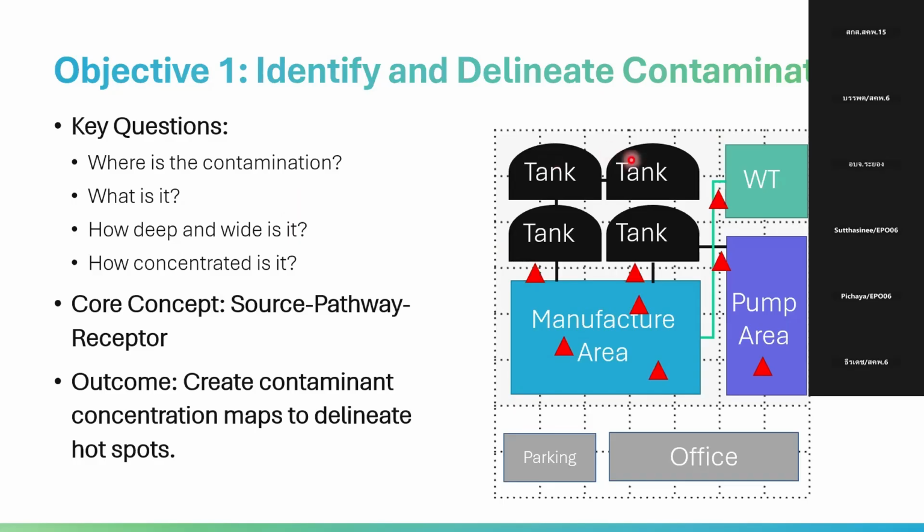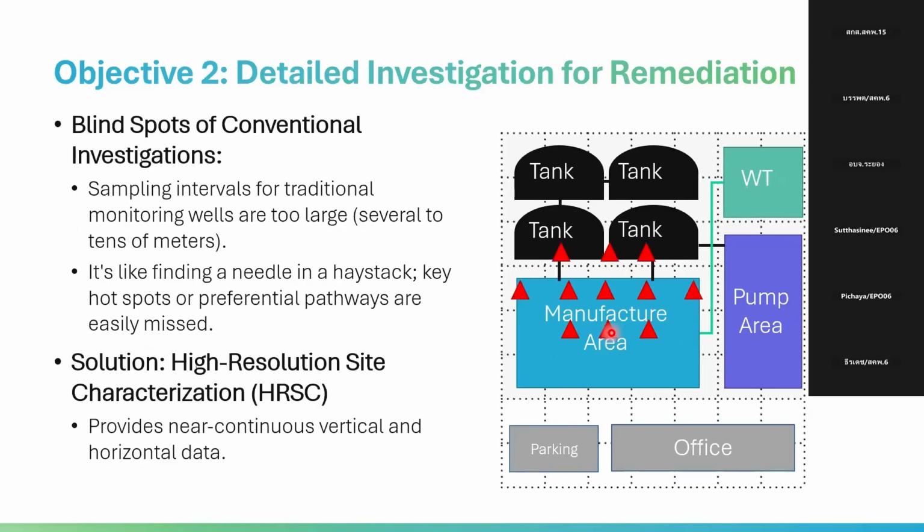So try to call different sampling like this, and you don't have to do a lot of sampling. Just use the judgmental method, taking some samples at the proper location and proper depths. You can get a very good result to identify the potential sources. And if you want to do the remediation, you can use the grid method, because you already know the contamination may be located here.